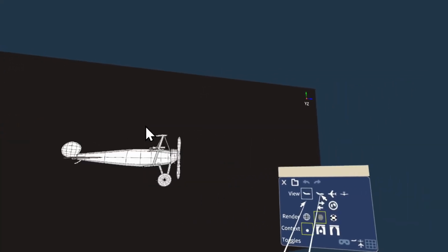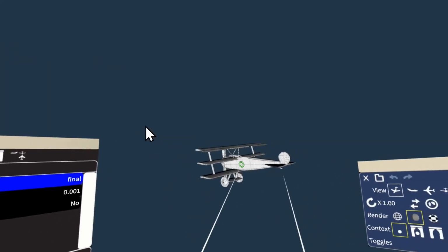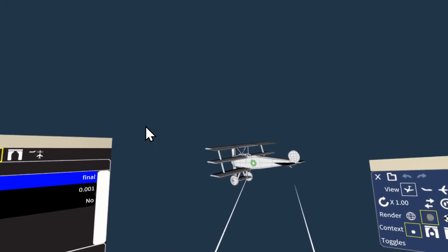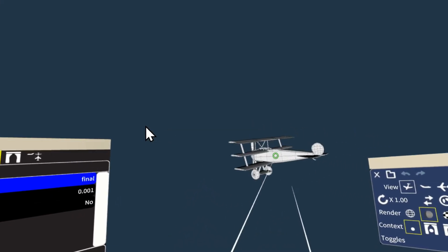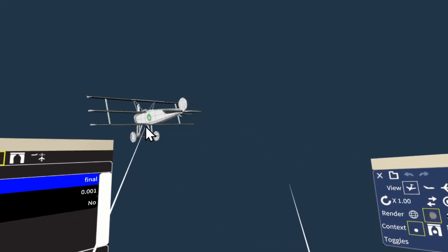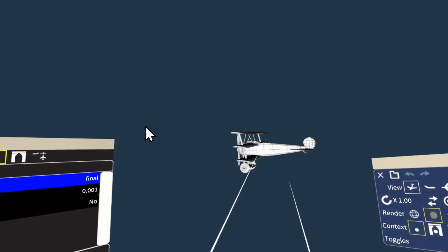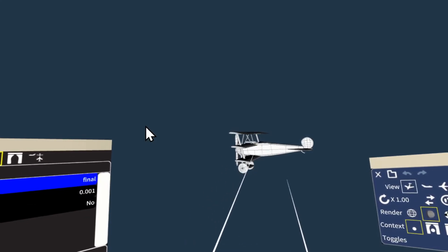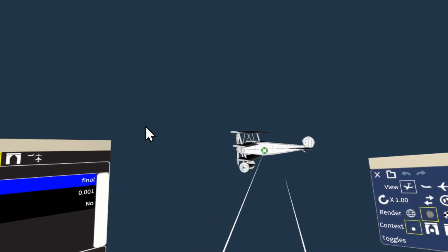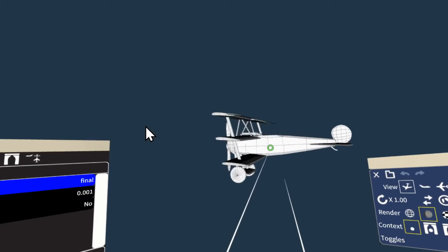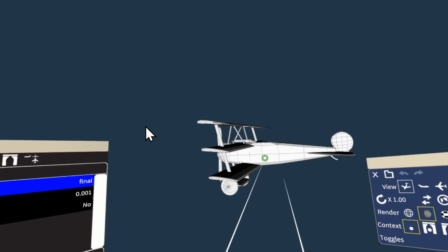Moving to the VR view, it works in a similar way, except that to pan or rotate, you have to have your pointer on the mesh. A green cursor will appear showing you when this occurs. You can then pan as before by holding the trigger and rotate by holding the grip. The zoom works slightly differently in the VR view. First of all, you must be rotating or panning for it to be active. Secondly, while panning, zoom will pull the mesh towards you or push it away. If you're rotating, the zoom will scale the mesh about the green cursor.